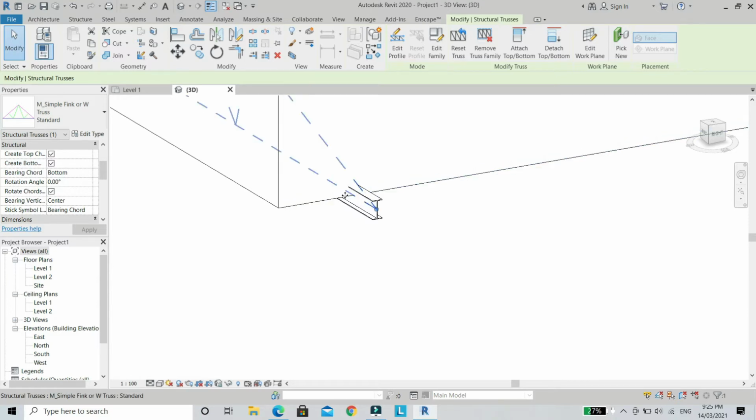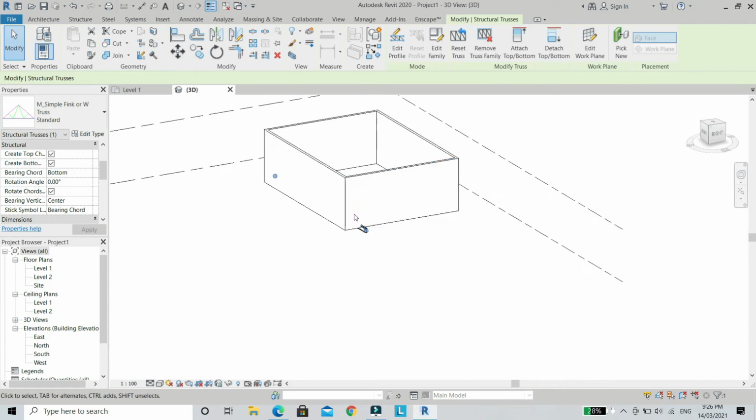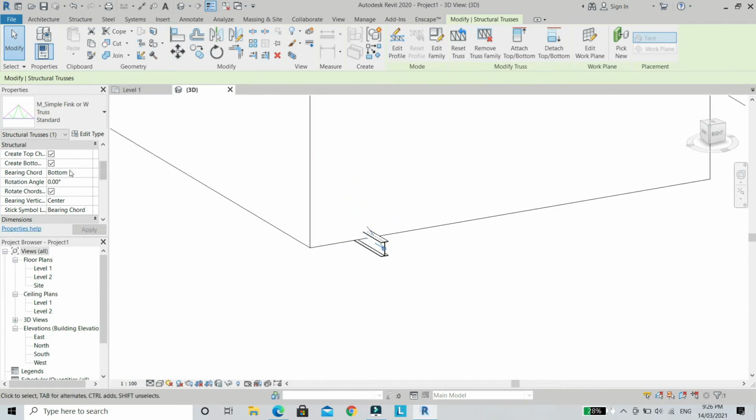If you can see here, once I put my cursor, there's a hidden line. That's the base of your truss. To make it up here, we can actually move this one or make the constraints move. So we can type 4 meters for the start level, same as here.